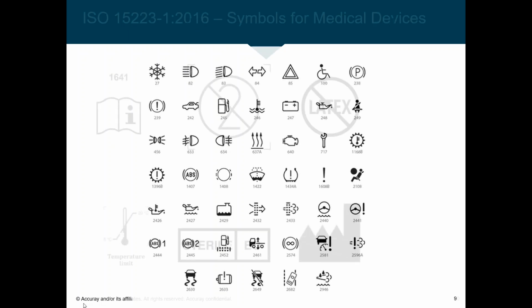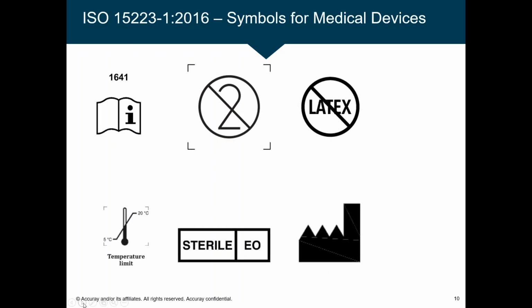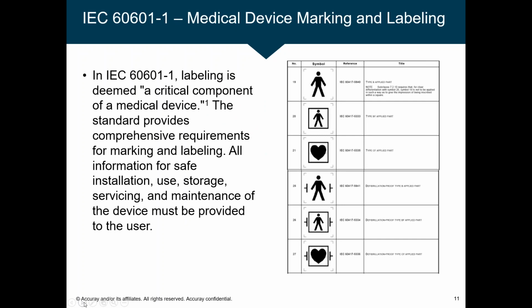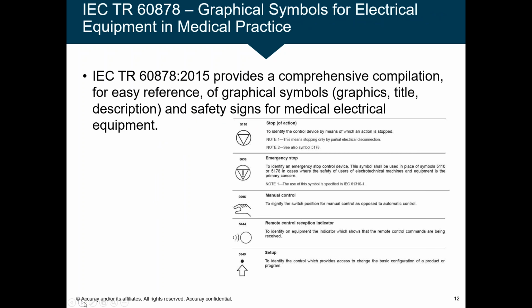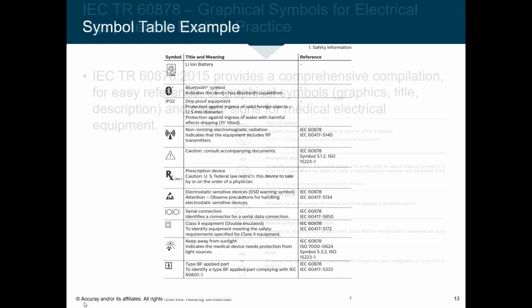But in your case, how I would handle that is say, this is how we're going to apply the use of this symbol, and then just document it in one of your SOPs or work instructions. Oh, okay. You just get rid of that ambiguity and say, in our case, we're going to use the one with the line through it, which means do not reuse after 50 applications or something like that. You know what I'm saying? Then if it's in your SOP, that gets rid of that ambiguity and defines how your company is going to use that. Oh, okay, great. Thank you. Yeah, you're welcome.